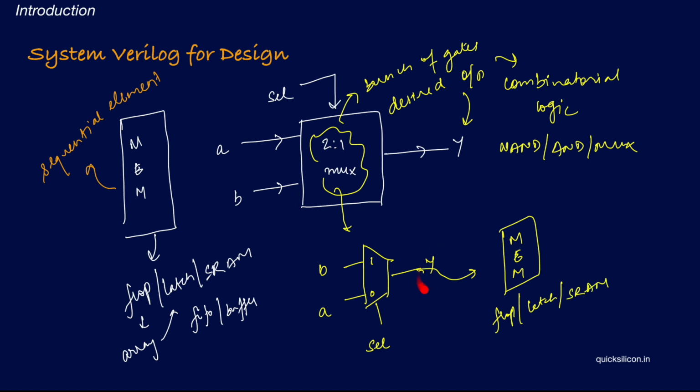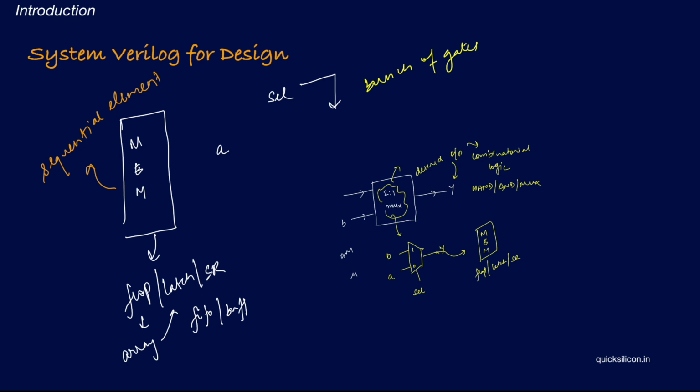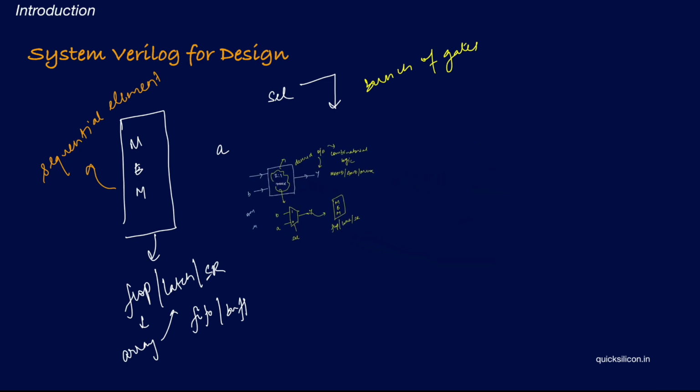Now, once you have written your output into the memory element, this particular memory element would again be read out for the combinational logic which is present in the next stage to produce the next desired output. Now, if you think about it and put all of this chain of elements together, what you will get is a series of sequential elements or the memory elements, and between the series of sequential elements, you would have some sort of combinatorial logic setting which will be producing the desired output for every stage.